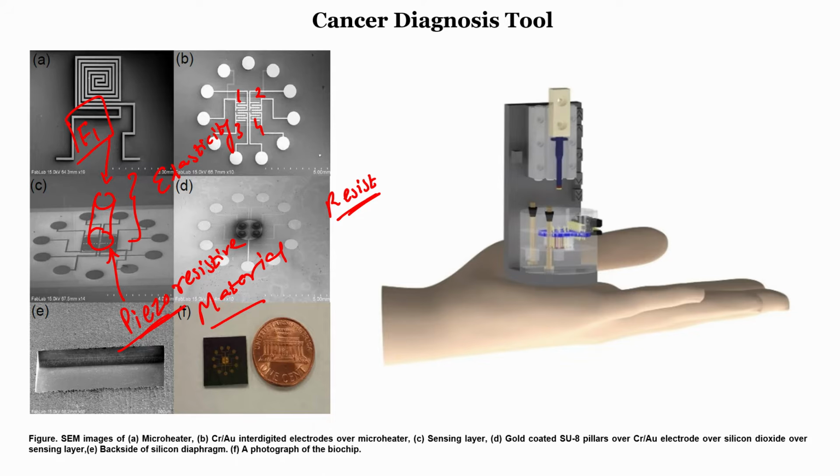The force that I am applying F1 and the force that the piezoresistor measures will depend on the elasticity or the stiffness of the material placed between the sensor and the indenter. Indenter is where you apply the force. This is where you can say it is an indenter. All right. So, now what will happen? From this we can measure the elasticity of the tissue.